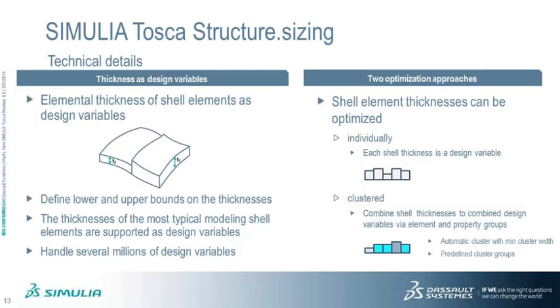Or you can cluster elements into certain sections by imposing that they have the same thickness. So probably this would be a solution that you would use at a later stage to ensure that your design is very near to the manufacturable final design.